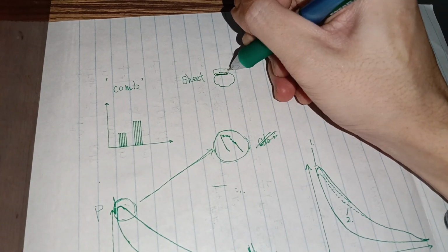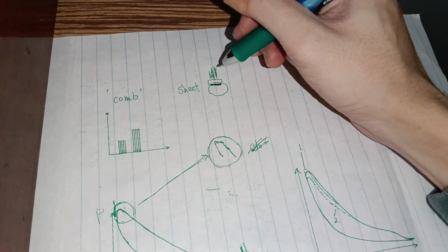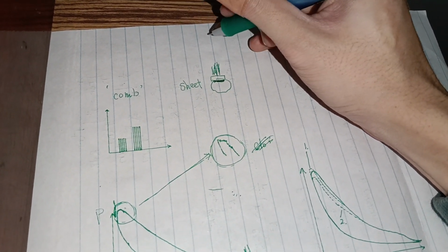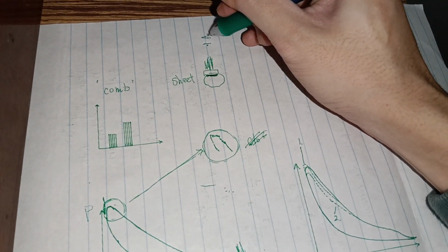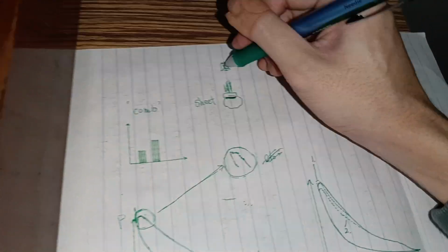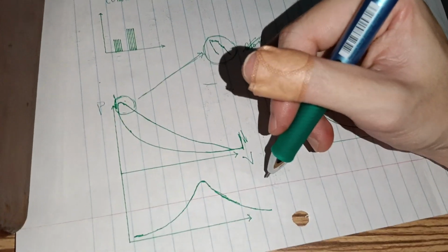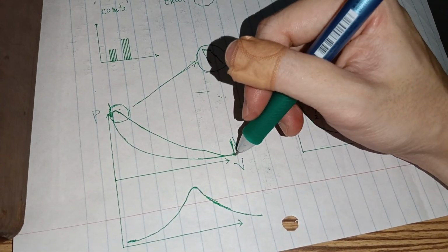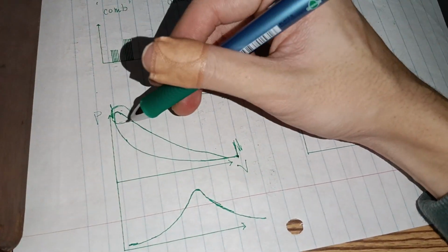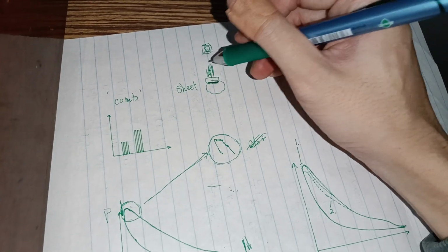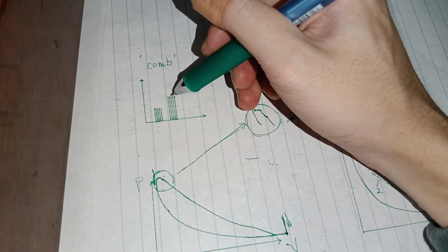In between the top of the crank pin and the base of the rod, they will add some shims to adjust the actual volume between the center of the piston and the cylinder head. This changes the volume of the cylinder when the piston is at top dead center or bottom dead center, and the compression ratio is changed in this way.